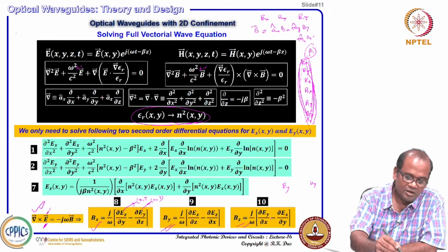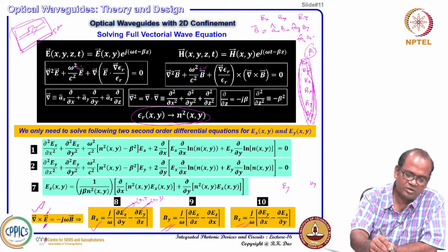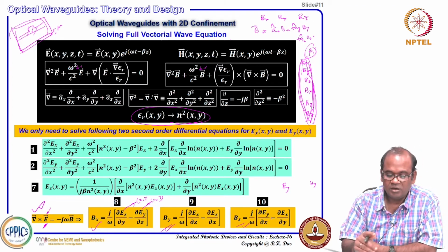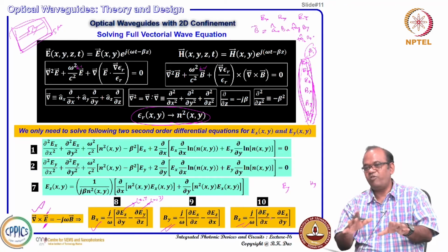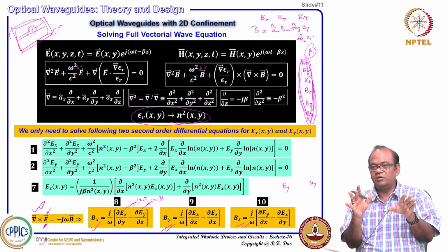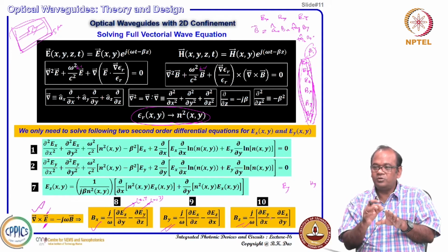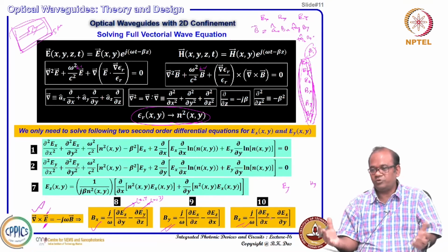So, if you have a waveguide cross section, including buried oxide and then your core cross section etc. together, for example, if it is a 5 micrometer by 5 micrometer area you are solving, then you can get different types of solutions. It is very fast, but if you have very large structures and your element size is infinitesimally small, then you have to handle a huge amount of data that may take a longer time to solve.